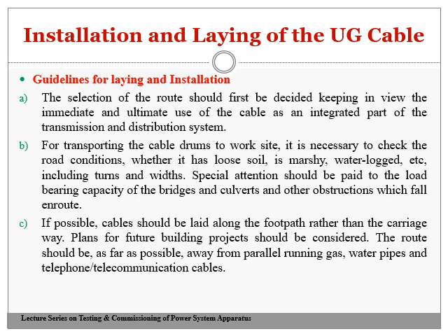You should know the road conditions over which the cable goes through the area. That has to be considered. Special attention should be paid to the load-bearing capacity of bridges and culverts and other obstructions which fall en route. Once it is transported, you should always take great steps to protect the UG cable against any damage until it is commissioned.